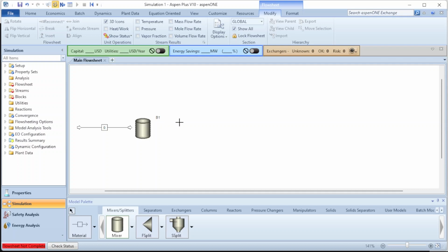And now you can see what I was talking about. This time around, I'm not supposed to give a name to my block, but rather the block name has already been given. So I have to deactivate the insertion mode. We will come here, cancel the insert mode. Then I want to rename this unit, this block, as Tank-A.